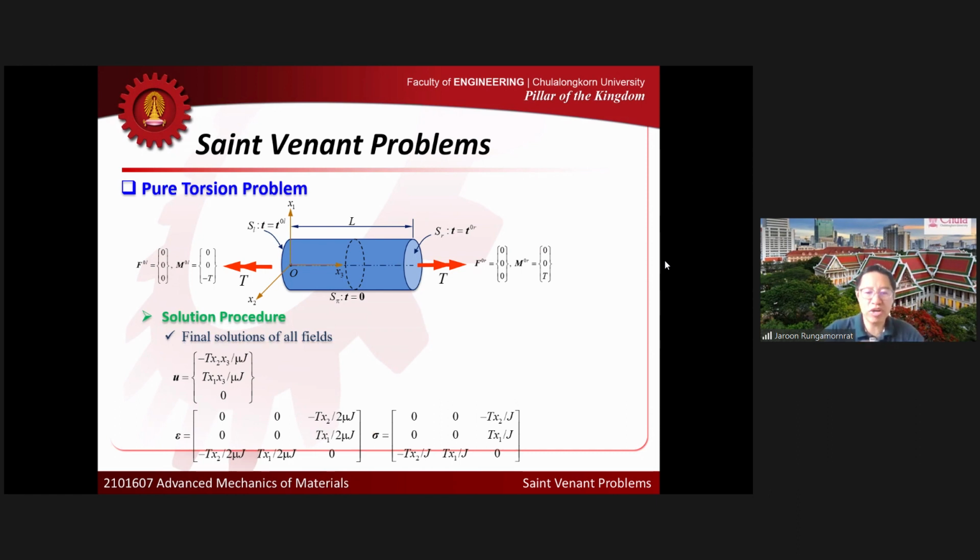So now if you look at the stress field that we got here, there's no normal stress. So when you apply torque, it simply generates the shear components, right, for the stress tensor. So we have only shear components, and one shear component disappears. This one disappears. You can see that. So that is simply the in-plane, sorry, the in-plane shear component. The in-plane shear component is 0, right?